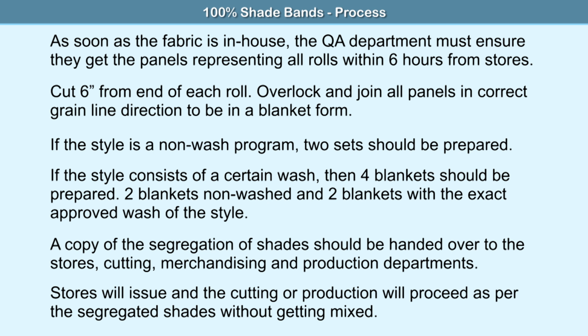Process. No sooner is the fabric in-house, the quality assurance department must ensure that they get the panels representing all rolls within 6 hours from stores. Cut 6 inches from the end of each roll.